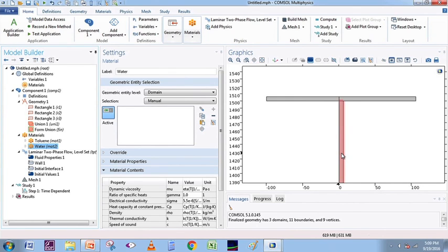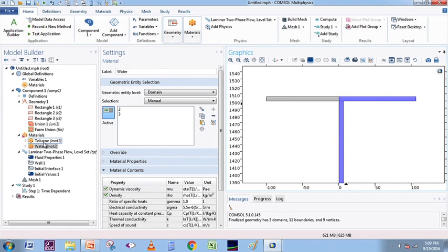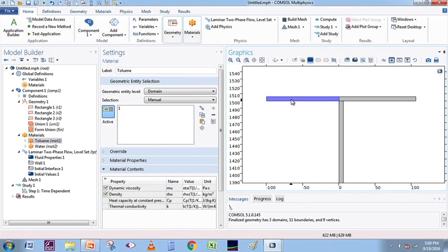Initially in this condition, our whole test geometry was filled with water, and from the left domain the toluene inlet was provided, and the left domain was completely filled with toluene. As we have learned from our theoretical classes, the flow patterns get affected depending on the initial wetting of the faces. So, we need to be very sure about the wetting properties and recheck them. Then initialize these two domains with water, as was the experimental condition, and the left hand side domain with toluene.